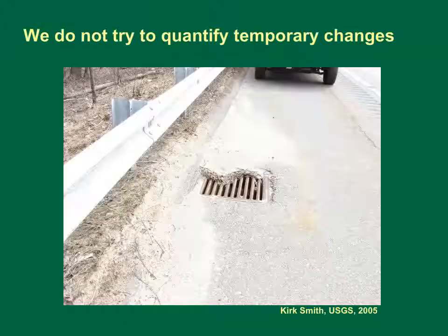In very small catchments, temporary changes in drainage area may be caused by clogging or surcharging of drainage inlets. This image from Route 2 in Massachusetts indicates how sediment and debris can dam up a storm drain inlet to cause bypass flows. When we do SELDM models, we must ignore such transitory effects. However, the population of runoff coefficients used to model runoff in SELDM probably include the effects of such processes.